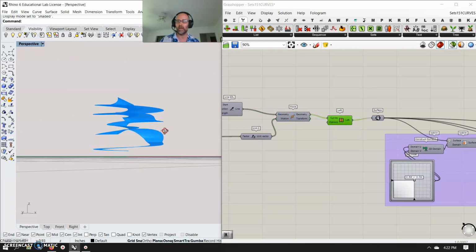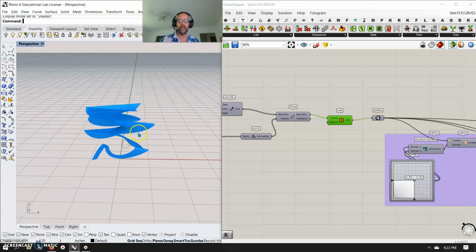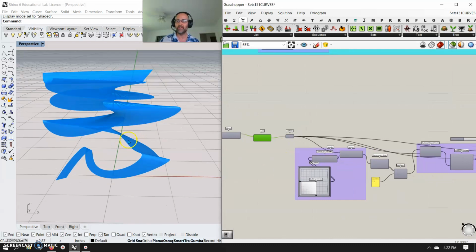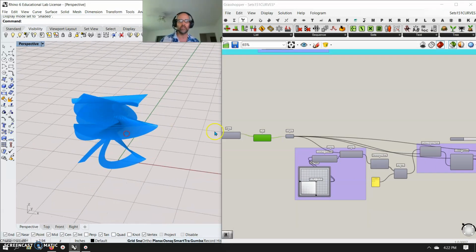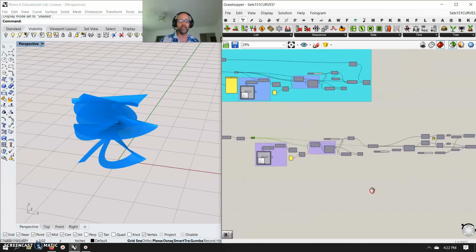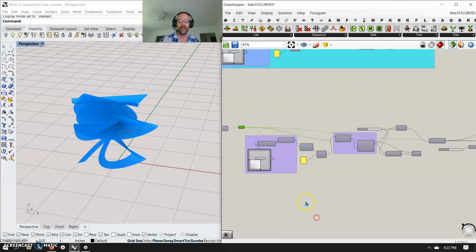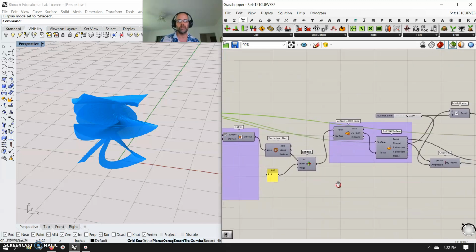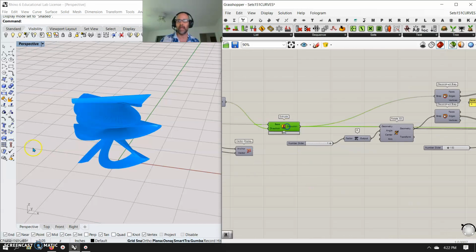Once you loft it, you get this wild curve that walks its way up as a ribbon tool cut out of steel. Now, you can find a way to bend that, work a 1/4-inch plate, and you've got some skills. I mean, you can always take these over the mesh, carve them up, weld them together, make the units. But as for a very parametric cool model surface, I then throw it through my similar algorithm that I did in all these top 3 exercises before this, dealing with curves. So I'm going to bring in that trim surface into iso trim, curve closest point, evaluate surface, and extrude. And bam, I'm left with it.